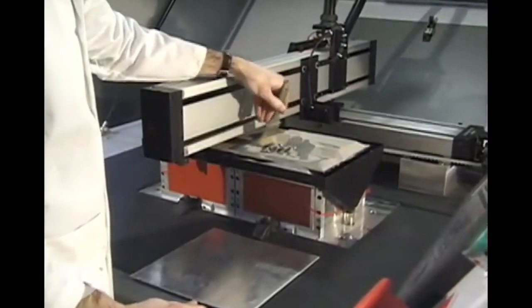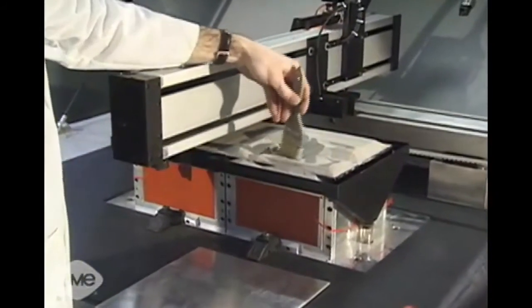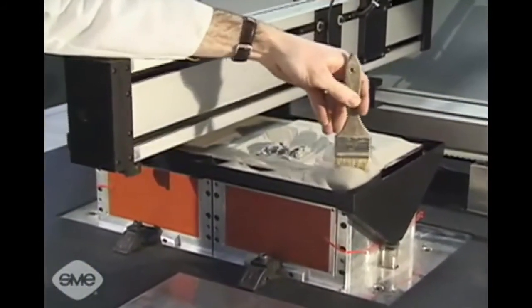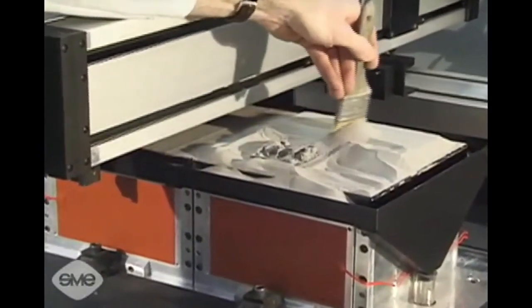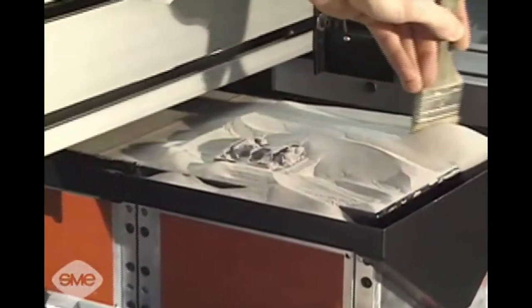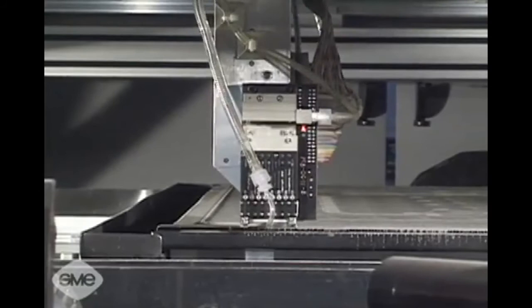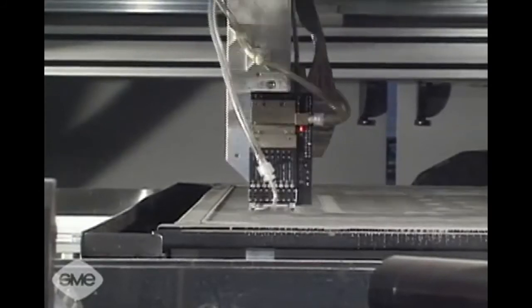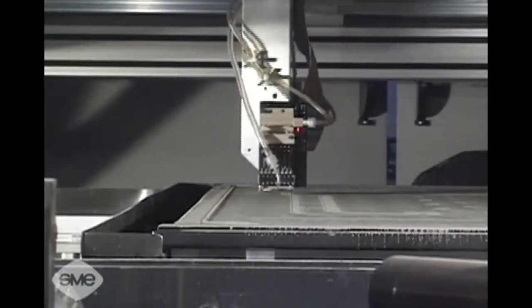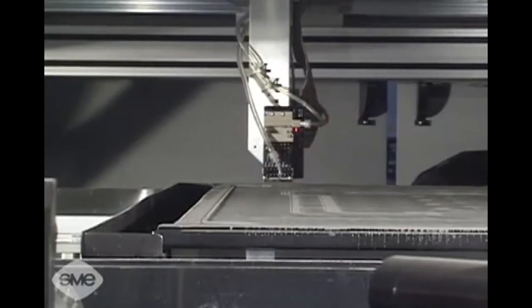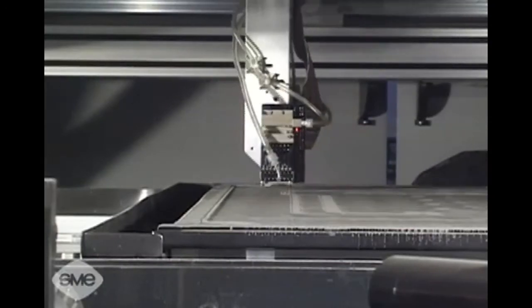Upon completion, models are sintered to remove the binder and bond the powder particles, and then infiltrated with bronze to substantially reduce or eliminate porosity. Besides the capability of making high-strength, durable models, no support structures are required. Tooling for plastic molding processes are a common application.